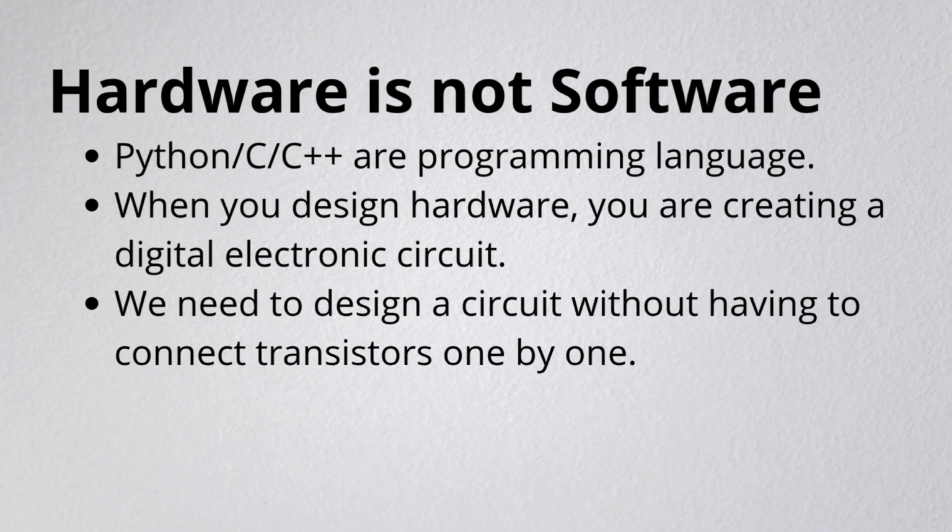Hardware is completely different. When you design a digital circuit, you are not writing a list of steps. You are describing a physical structure, a circuit that exists in silicon. And that circuit operates concurrently, in sync with the clock. Every signal, every gate, every register, all of them react on every clock edge. There is no interpreter running your code. There is no CPU deciding what to do next. The circuit just is, and it does what it does every single cycle.